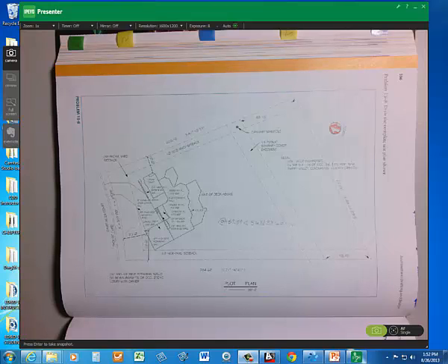Remember to set up your sheet as decimal units, and your degrees would be surveyor's units, and you want to set up the precision on the surveyor's units so that seconds are displaying, just plain whole number seconds.